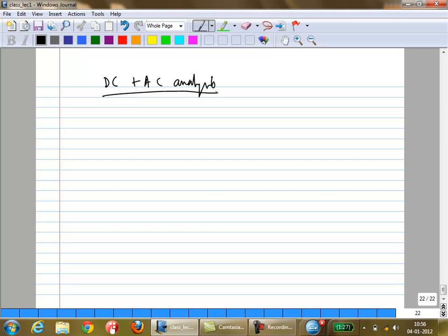In the DC picture, ignore all capacitances, because it's DC, so all capacitances are open circuit. Next, when you do AC analysis, you put in the appropriate capacitances. If you have very large capacitances, they are shorts. And all these GM, GMBS, all of them are incremental values. Is that clear to everybody? I assume you should all be totally clear about this by now.